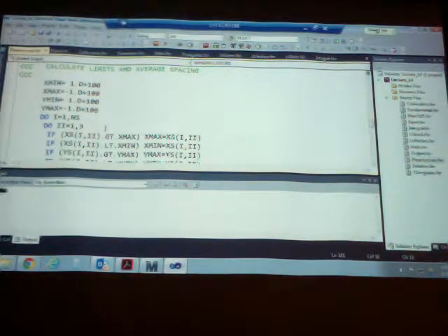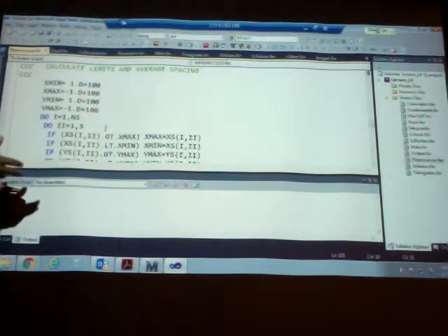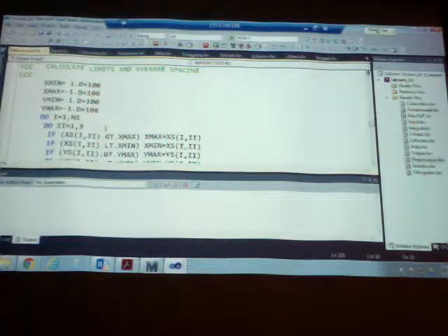And it throws points depending on the discretization level. So it calculates the size at which every point is separated from each other, the average size, and it's going to use that same average size to throw in internal points. So the higher the discretization you use, the more internal points it's going to throw in, just to keep some sort of consistency.